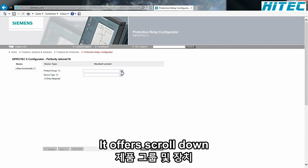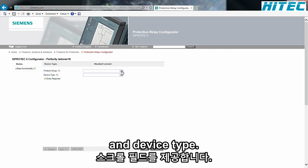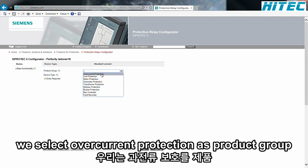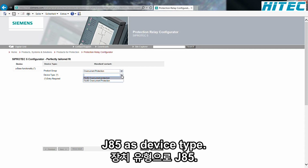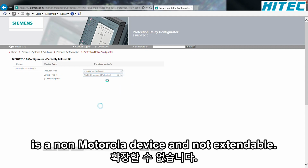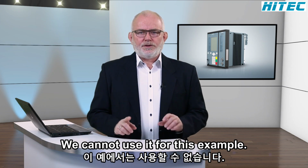The following page will bring you to the actual configuration process. It offers scroll-down fields for the selection of product group and device type. According to the specification, we select overcurrent protection as product group and 7SJ85 as device type. The 7SJ82 is a non-modular device and not extendable. We cannot use it for this example.